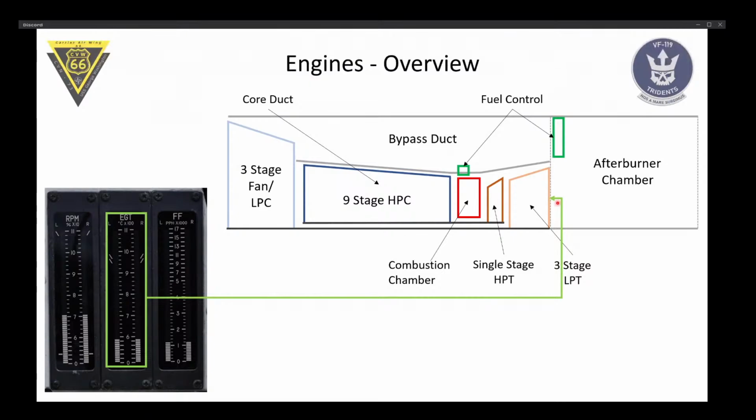So okay, exhaust gas temperature, right? These turbines are made of some kind of alloy which is very heat resistant, but not infinitely heat resistant. And we want to know what temperature is basically around the turbine. We only measure the exhaust gas temperature behind the three-stage LPT, because the temperature here correlates strongly with temperature here. And there are certain limits, which are indicated here, which is 935 degrees.